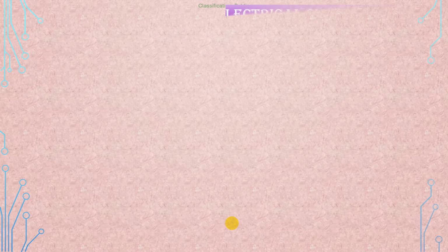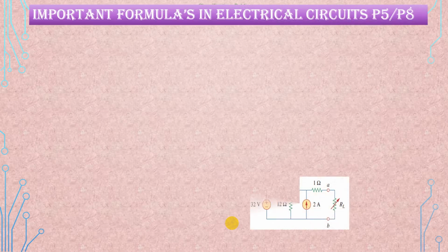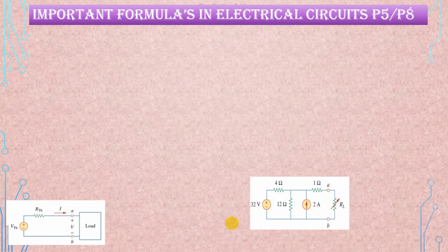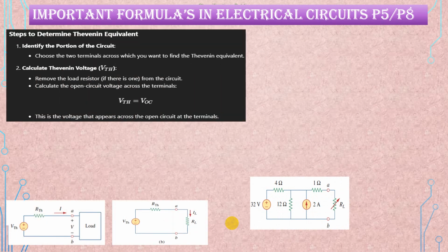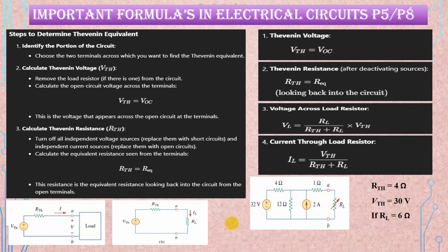Okay, last slide we can go. Okay, here now we go. Oh yeah, last 2 slides. Thevenin's theorem, Norton's theorem is there. I will not go into Thevenin's and Norton's in depth. Just remember that for Thevenin's resistance, generally we will find how: just remove that load resistance from the big circuit, where we want the analysis. Remove that resistance.